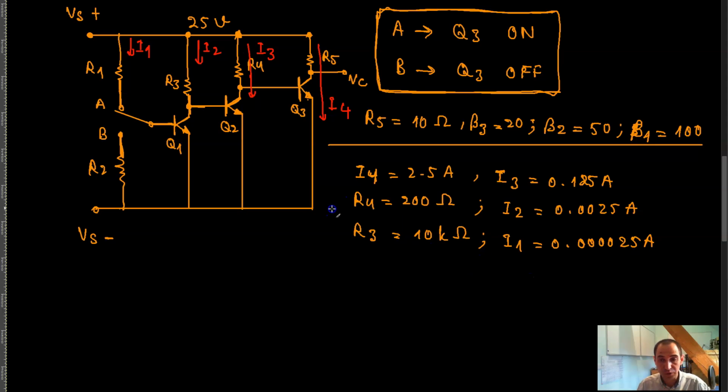It's 25 microamp. And so if I choose this resistor, I apply Ohm's law to R1, and again the whole supply voltage is across R1, so that's 25 volts is equal to this current, 25 into 10 raised to the power negative 6 amp, times R1.